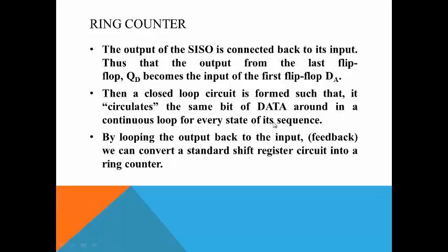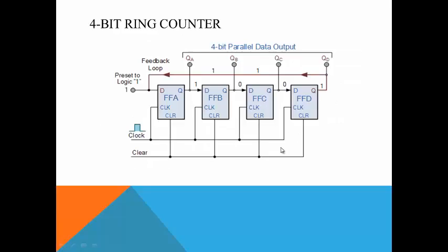This forms a closed loop, and whatever you give can circulate inside the flip-flops, inside the 4 flip-flops. The looping of the output back to the input is called feedback, and you can convert a standard shift register into a ring counter this way. So see the configuration.